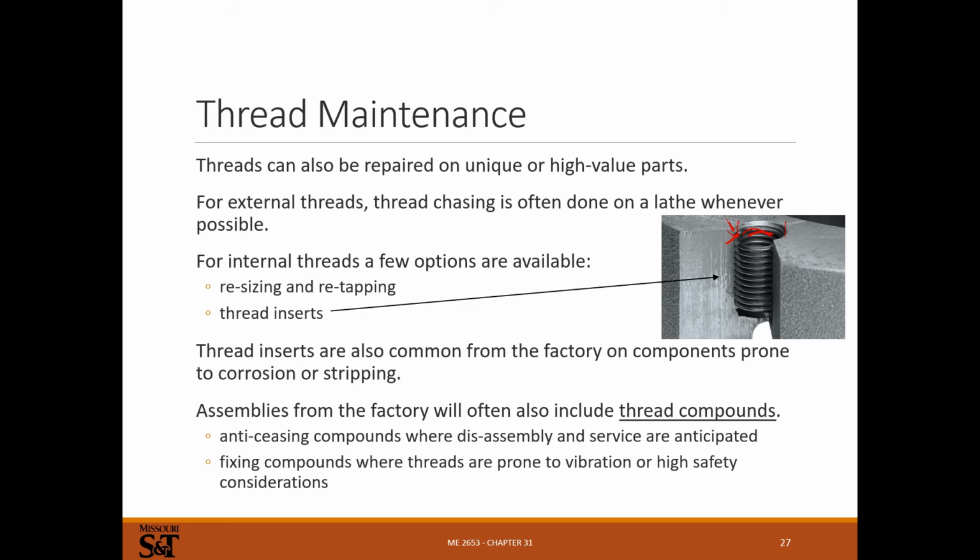In really, really critical applications like connecting rod bolts, you might actually measure the stretch of the bolt, the deflection of the bolt, with some kind of dial indicator to guarantee that you've got a specific amount of stretch, especially in torque to yield fasteners, where you torque a fastener to the point where it stretches and permanently deforms, it plastically deforms. That's one way of guaranteeing a clamping load in very critical applications.